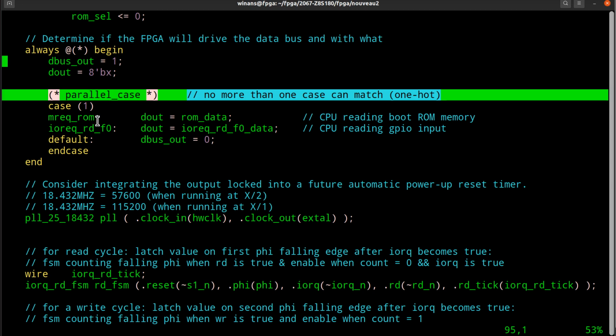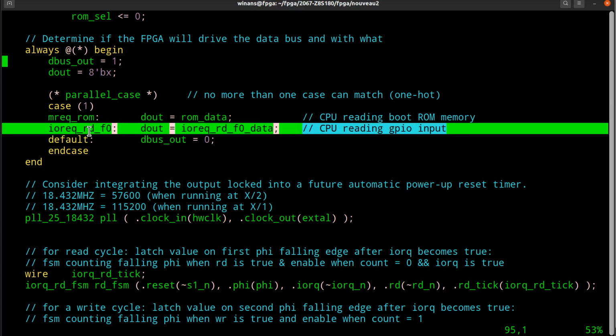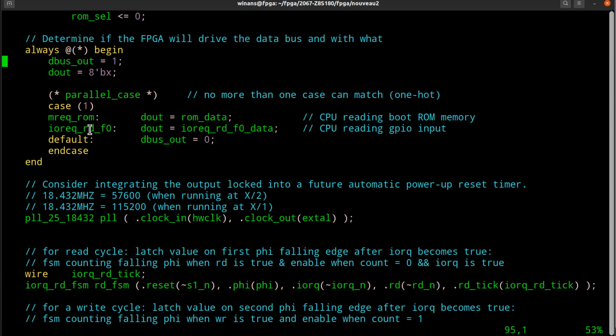without this, what you're doing is you're building a multiplexer, and you have to convert this into, like, address 0 and address 1 to pick one of the n inputs of the mux. With this thing present, you don't have to do that. You can throw away the decoder that's buried inside of the multiplexer and use these single-bit signals to reach into the AND gate that drives each one of the outputs of your mux.